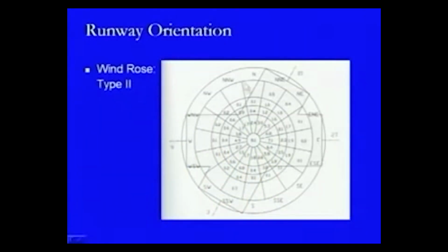This is one of the typical diagrams where we have north, and these radial lines are drawn from the center for this direction and the other direction, that is north and northeast. So, this is the center, and because these concentric circles are related to the speed, we have the cells. So, this is one cell, this is another cell, this is another cell, likewise. Whatever was the value related to north for the first category, then for the second category or for the third category has been noted. Similarly, it is being done for the rest of the cells.